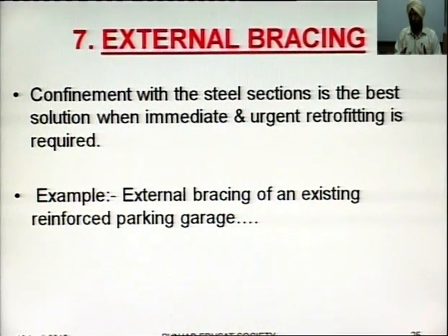You will see how we do the external bracing here. In this technique, we are providing confinement with the steel sections, and this is the best solution whenever immediate and urgent retrofitting is required. Repeating it once again, the confinement with the steel sections is the best solution whenever immediate and urgent retrofitting is required. Taking an example of external bracing of a reinforced parking garage.